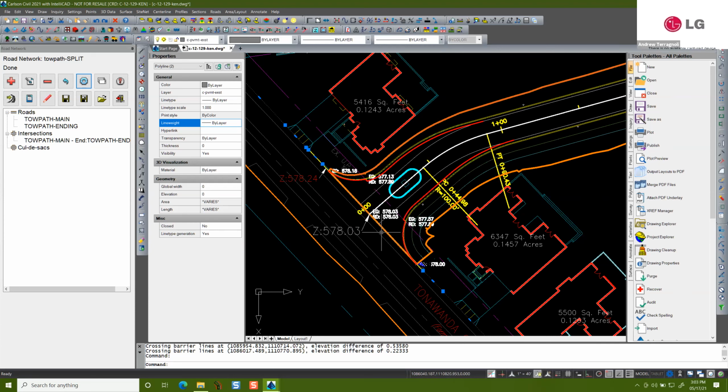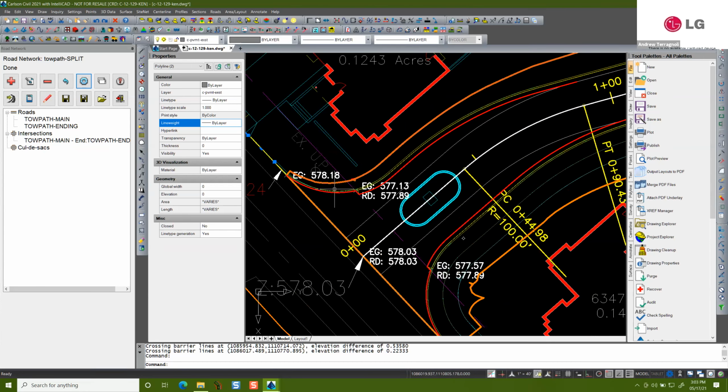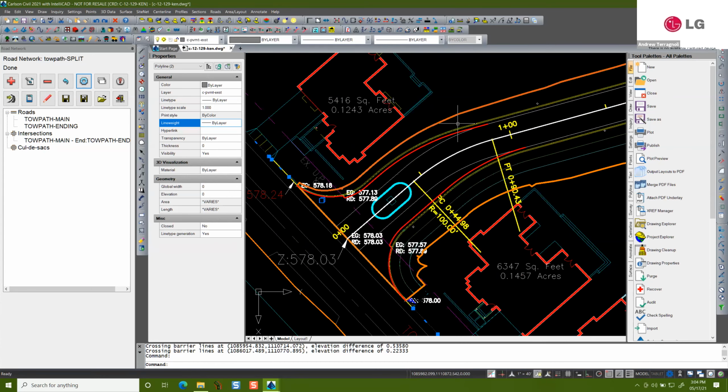And so it goes from where it thinks it is out here, it knows where it is out here on this road, and then it takes that radius and all that, and calculates where that's going to go, and then it starts building that in at the radius. But we don't have just a simple curve here. We've got a curve, and we're wider, and then we come back in here. So after we get past the circular part of this curve, we still have to do a transitioning template. Yeah, we'd have to do a transition template.